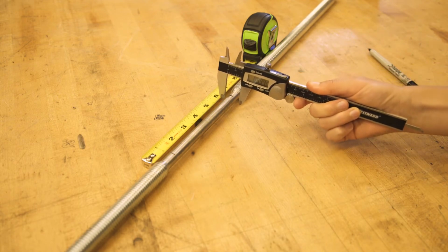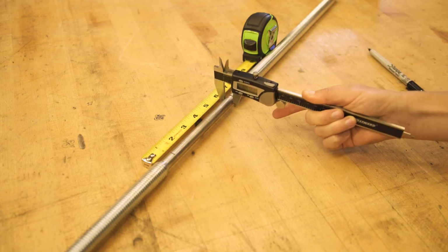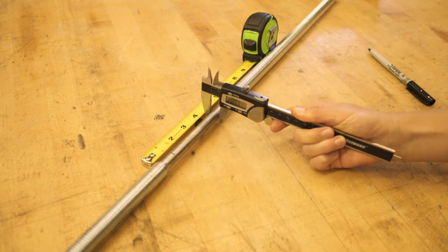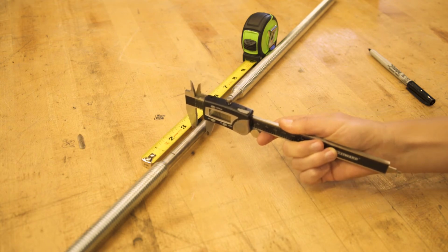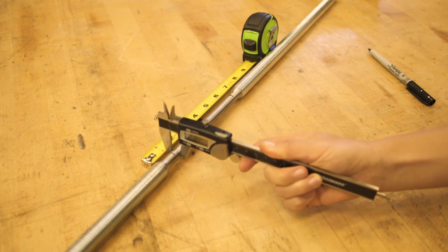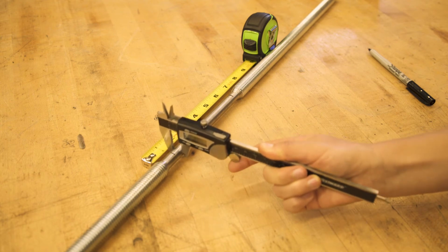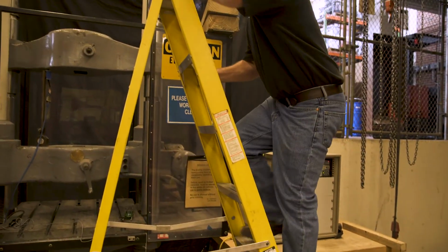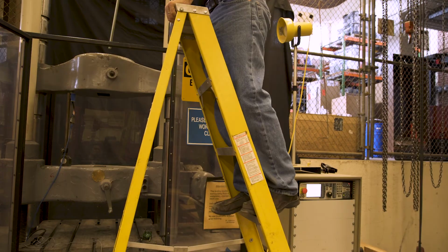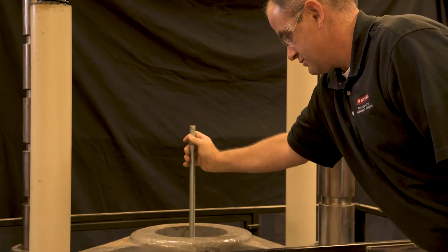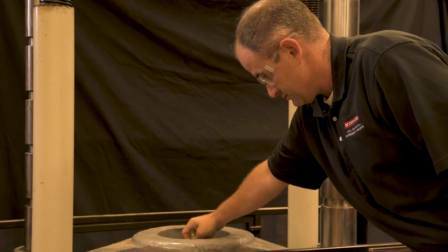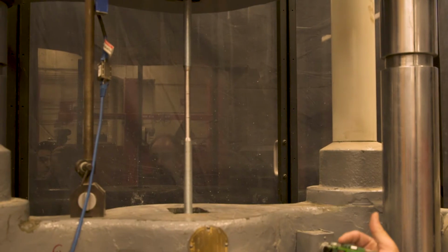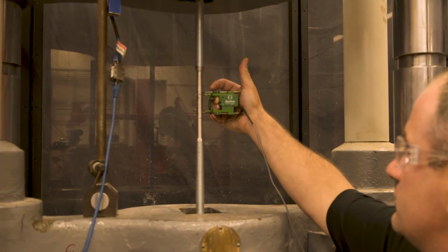Measure the diameter of the specimen at 4 locations within the gauge length using the calipers. The specimen is not perfect, and therefore minor variability in the specimen diameter is expected. The TA will secure the specimen in the servohydraulic test system while the machine is off. The TA will then affix the extensometer to the specimen.